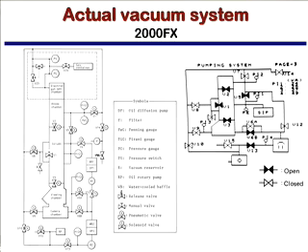Okay? It turns out that V6A and V6B, this is a bigger opening and a smaller opening, I believe. And I think the idea here is that if you are still trying to pull this thing down to vacuum, you first use this one, and then you switch to that one so that you lower the load on this pump and can use it to back up this diffusion pump as the thing works. Okay? Anyway, there's a fair amount of complication in all of this, in terms of watching all of these things.